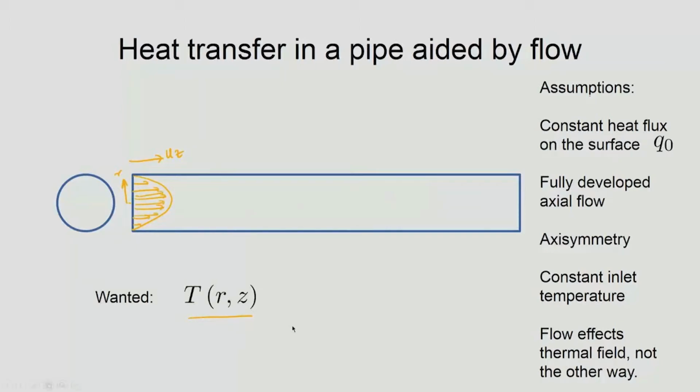Okay. So, this profile is going to affect the heat transfer, and we say that the liquid that is entering is at a temperature T naught, and what is coming out at any z is T(z), which is then a function of r. That means the temperature is a function of r and z, and the temperature is changing because there is heat coming in through the periphery. Through the circumference we are getting heat that is given as a constant heat flux q naught. So, remember it is a constant heat flux on the surface, q naught, problem.